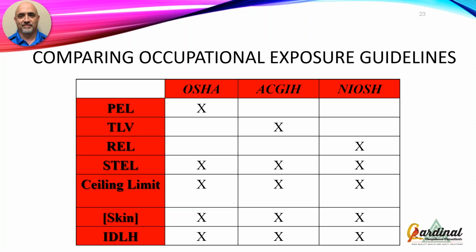Use oxygen in confined spaces as a good example. 19.5% to 23.5%. Below 19.5% is considered IDLH. You know what though? At 16%, I start having labored breathing. Look at myself now, 7%. Yeah, I'm going to start going into convulsions. I'm going to lose consciousness, things like that. So again, the way I teach on this is, look, you're at 19.5%, that's my limit. You're at 19%, don't panic, only get yourself out. You're at 9 or 10%, run. Okay, so that's kind of how you have to look at this, and it's for any chemical.